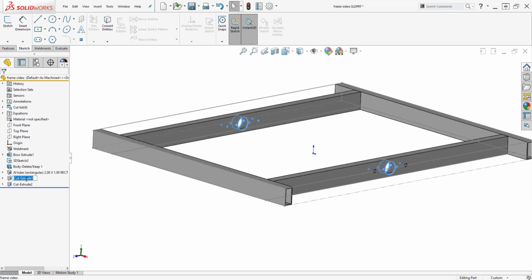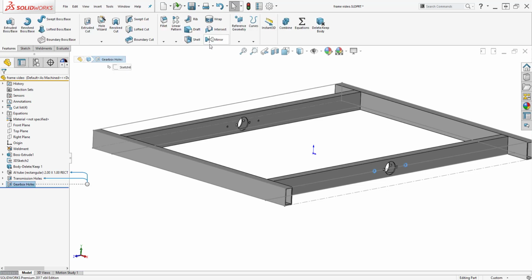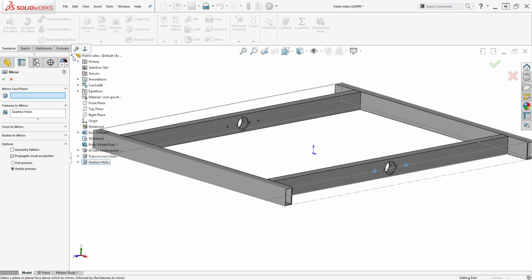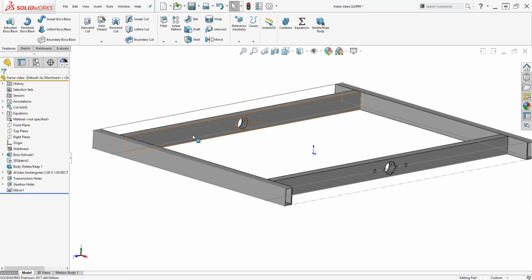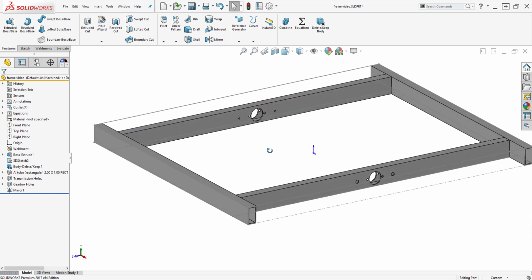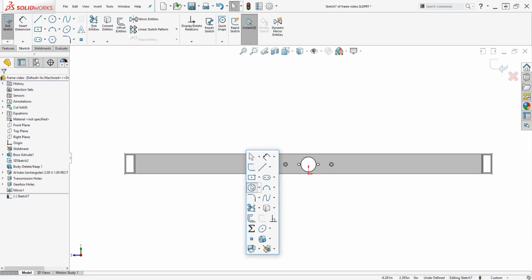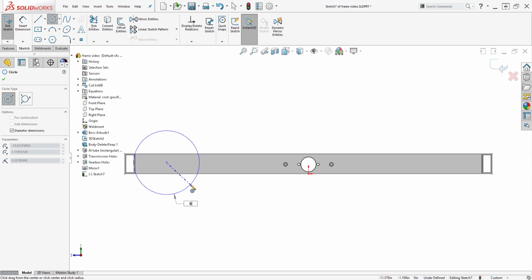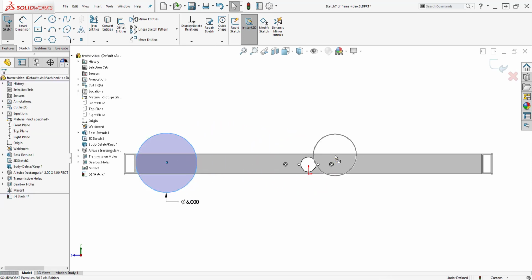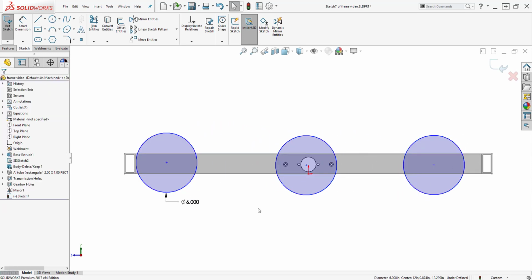That is the hardest part of the drive rails done. Now we just need to calculate wheel centers, which hopefully you have some idea of from the last few videos. If not, we can use this model to verify the clearance around obstacles that we talked about in the part 1 video. Since we're going to be using roller chain, we can calculate the center distances for a respective wheel distance and get a pretty close guess on how long a chain needs to be before it gets cut. This is a good practice, but not many teams actually do this. They just kind of grab the chain, cut it to size, and then they tension it afterwards.